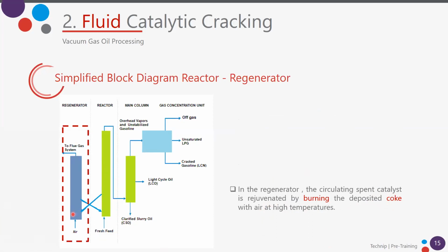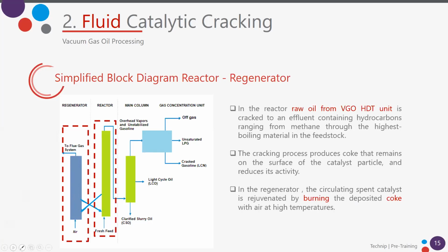We will see it in more detail in the next slide, but the catalyst with the coke will go through the regenerator, and we will burn the coke here, and we will send the regenerated catalyst again to the reactor.